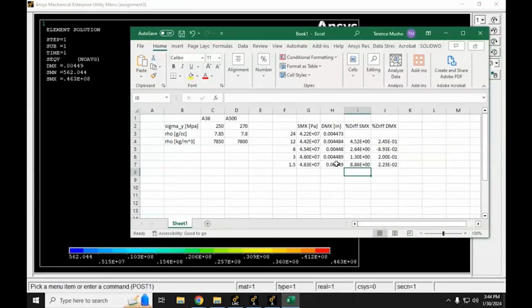This is kind of a scary realization for people who maybe have used finite element analysis and just used the default mesh in SolidWorks and went with the result, right? You could be off by 10% in terms of your stresses or more. All right.